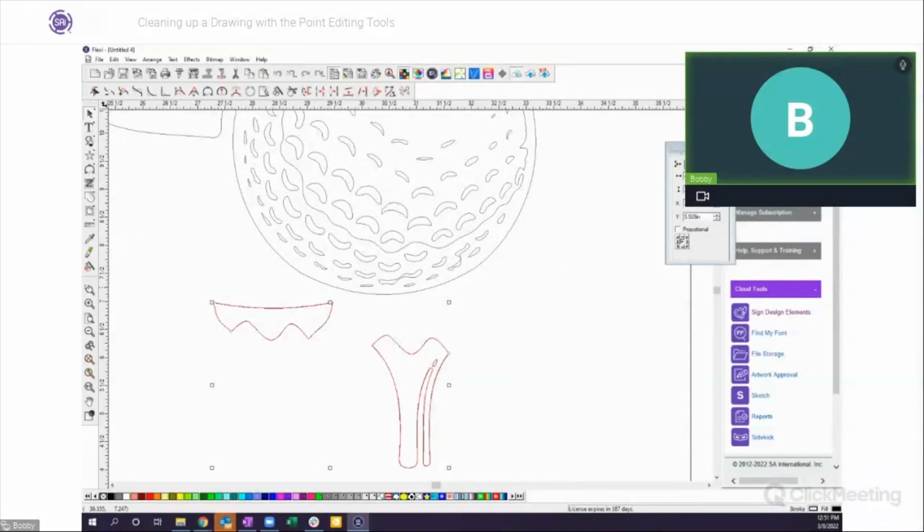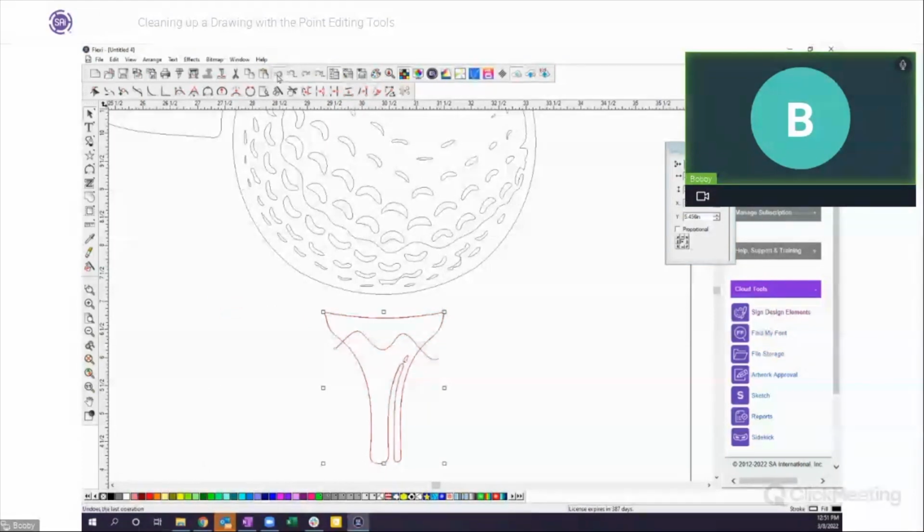All right. And then the other thing that we want to show is my scissors tool. So how are the scissors different from the cleaver? Well, as you notice, the cleaver filled in the line when it did that. The scissors tool does basically the same thing. However, when you cut across with the scissors tool, you notice it doesn't fill it in. So I basically cut that apart and made two different line segments that I now have here. So that is the difference.